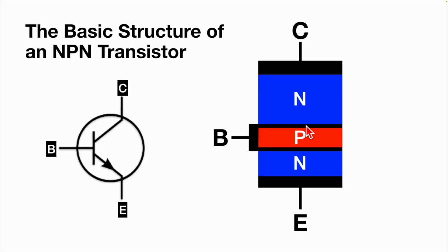And so this is indeed what happens. So between the collector and the base is a capacitance, just because of the design of the transistor. And of course, you won't be surprised to hear that it's just the same between the base and the emitter. There is a capacitance that exists there.